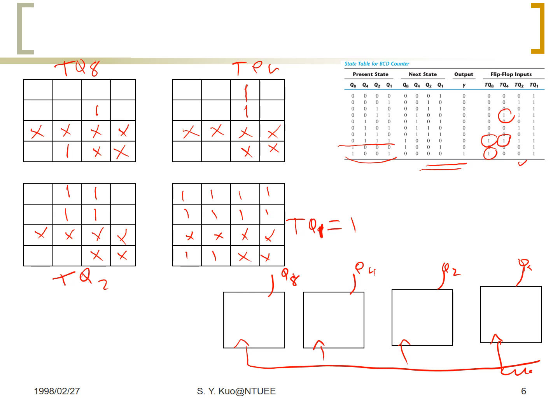And finally, the T of each flip-flop will be implemented as we can derive from these different Karnaugh maps. So this is one as an example here, and here we have this loop and this loop, and here we have this loop, and we are done with the design.